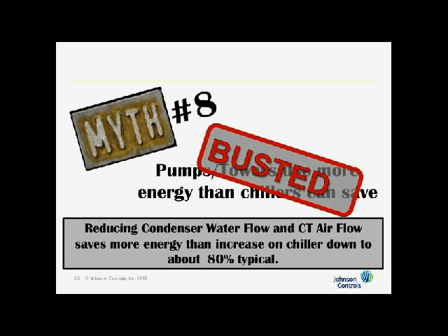And that means that myth number 8 is busted. Reducing condenser water flow and cooling tower airflow does save more energy than the increased energy on the chiller, down to about 80%. Now, if you go too far, then yes, it will increase. But we found that there is an optimum condition.